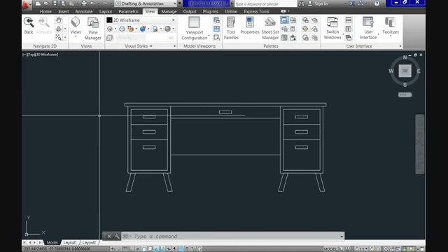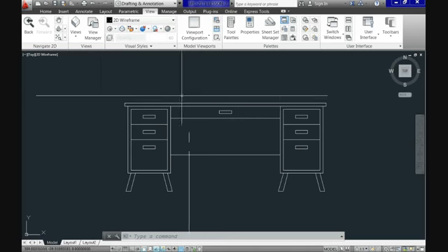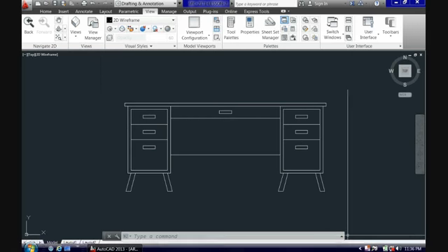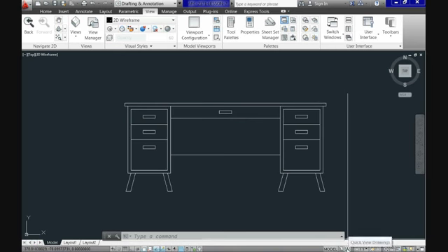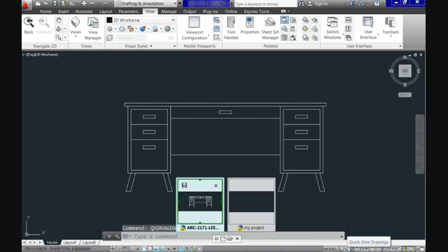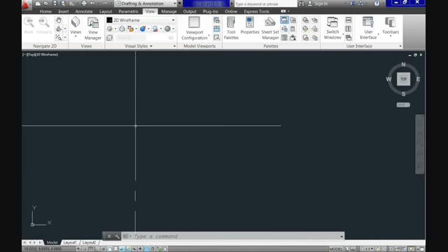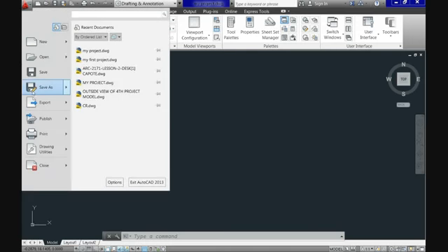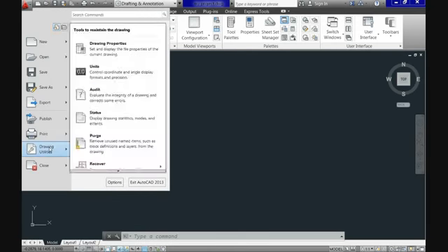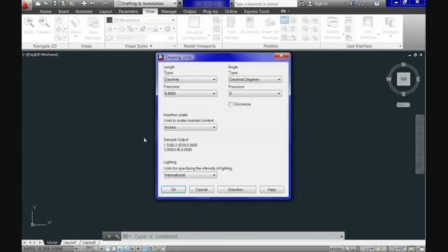However, when you got the new drawing, in this case the template, it has its own drawing units. AutoCAD by default comes up with decimal system. It's going to the application menu button, we click there, we go all the way down to drawing utilities, we point at it, and on the right you see the second from top to bottom is units.